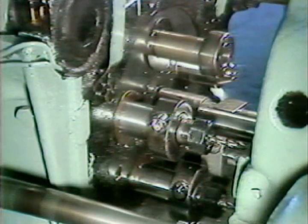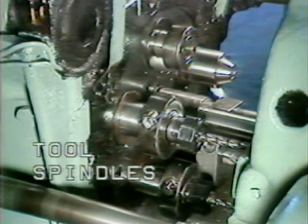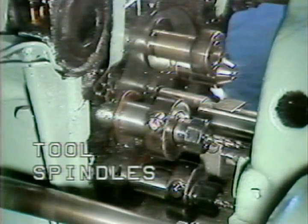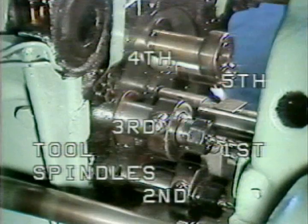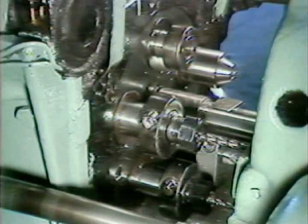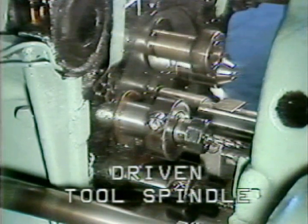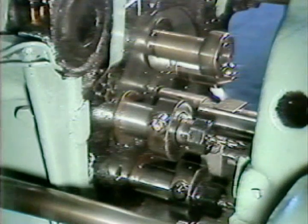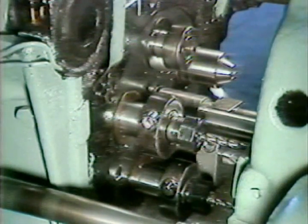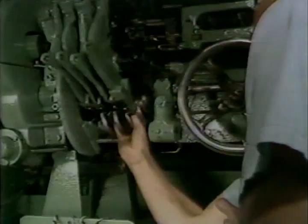The second type of metal cutting components on the machine are the tool spindles. There are 5 tool spindles. Their purpose is to perform all end work during machining. Examples of this type of work include drilling, reaming, broaching, recessing, and threading. Some machining operations require the end tools to rotate. Normally, all except the first position tool spindle may be driven for this purpose if necessary. The cross slides, tool arms...